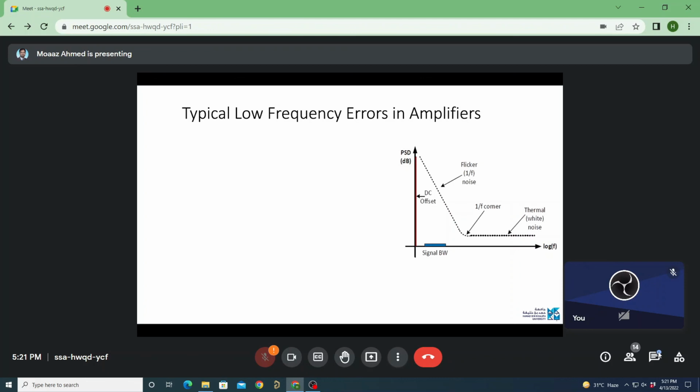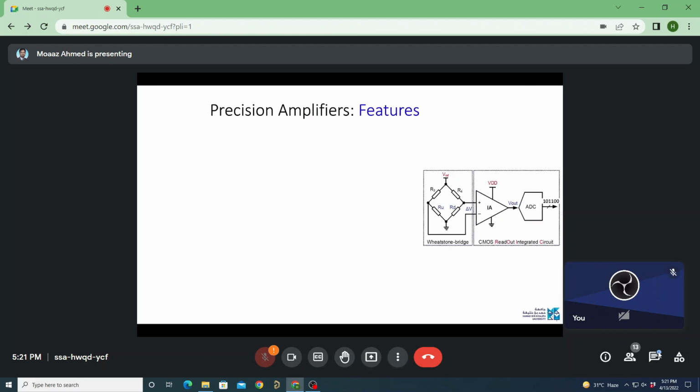All the applications that you have, like laptops and all kinds of sensors, have these instrumentation amplifiers because they are the foremost block. The world is analog, as you would have heard so many times. All these analog signals are very weak signals, and you need to amplify them. Your first friend, which interfaces with those sensors and gets this weak signal out for digitization by the ADC, is this block, the instrumentation amplifier. So you find it in ECG amplifiers, EMG, all these biomedical applications.